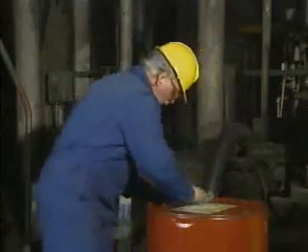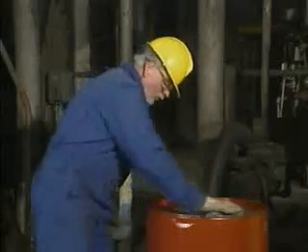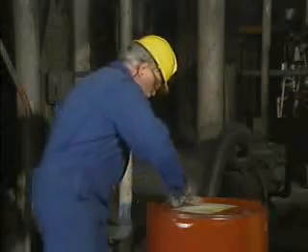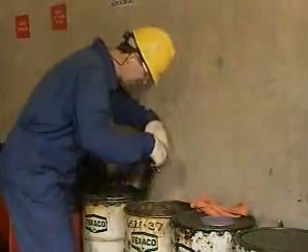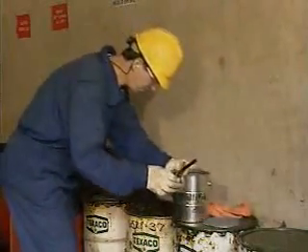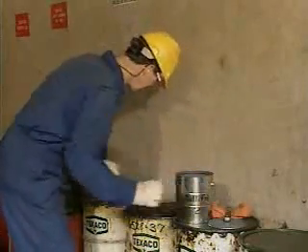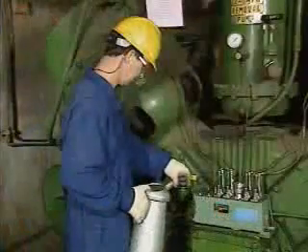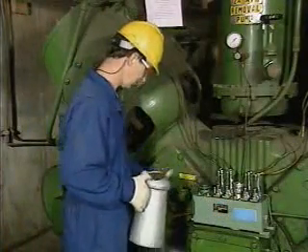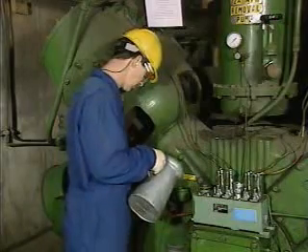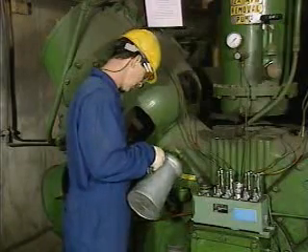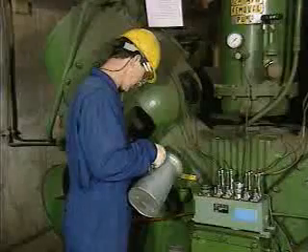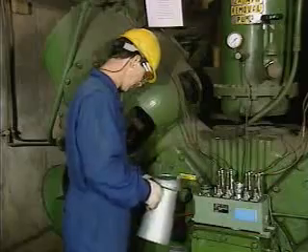As a rule, a lubricant container should be cleaned before it's opened to prevent dirt or debris from the container getting into the lubricant. When a container is opened and lubricant is removed, the container should be resealed as soon as possible to protect the remaining lubricant from contamination. Different lubricants may have incompatible additives, so when a lubricant is added to a partially full system, the type of lubricant that's added must usually be the same as the type of lubricant that's already present.